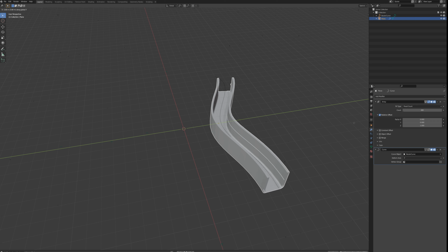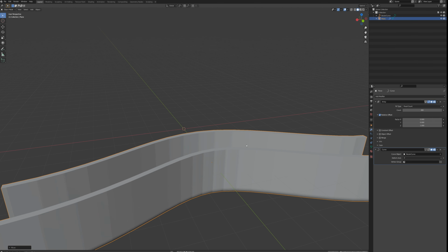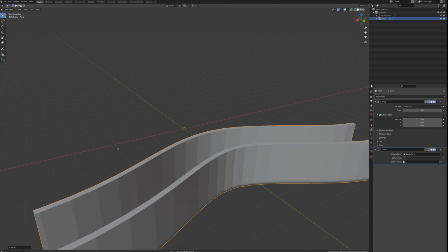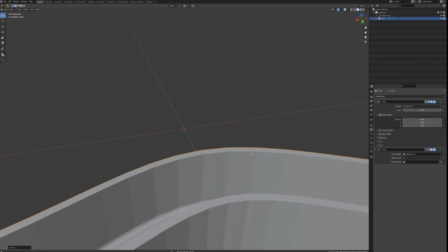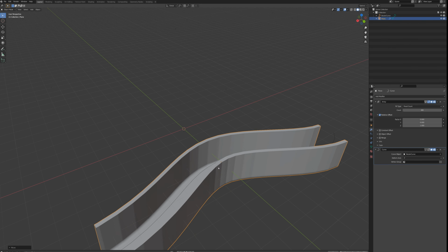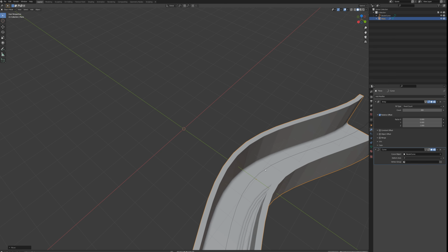And I'm just noticing one thing here. Okay, so I can see these sort of hard lines here in the edges of the walls, and so I made my cross sections pretty thin, and a lot thinner than this. And so the reason I'm seeing this is because the bezier curve that we're applying, that we're setting as our curve object, only has a certain resolution, and you can see sort of those same hard edges, hard corners in the bezier curve if you look close.